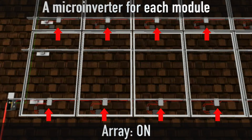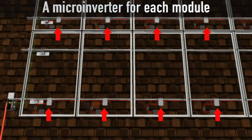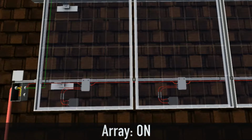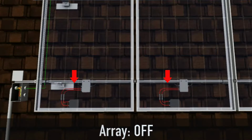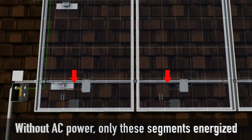In this type of system, because the microinverters also require AC power to run, when you shut off the main power to the building, the microinverter shuts down. The amount of energized conductors within the array is decreased. The only voltage still present is the wires from each individual module to that microinverter. Additionally, they are not wired in series.